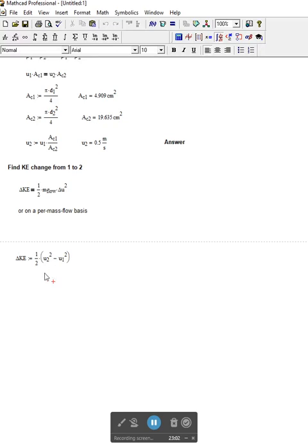All right, and so MathCAD, again, let me just type this. So capital D, KE, all right, that's my change in kinetic energy, shift colon, and then 1 divided by 2, hit the space bar to select that whole fraction, times, and in MathCAD you can use parentheses and brackets, just like you do when you're writing equations by hand, times U dot 2, and then everything is selected there.